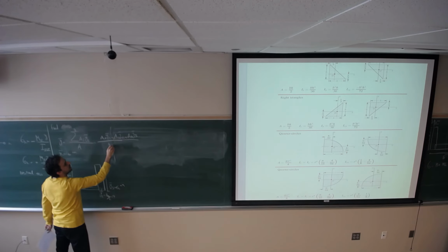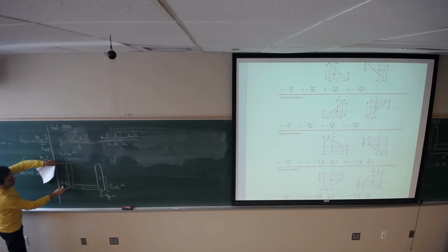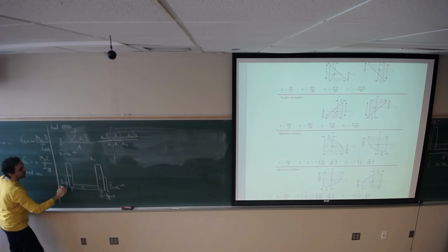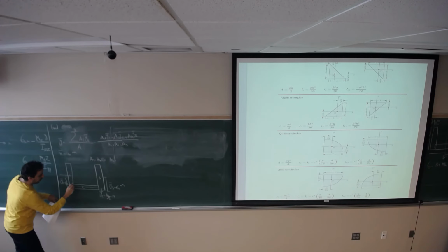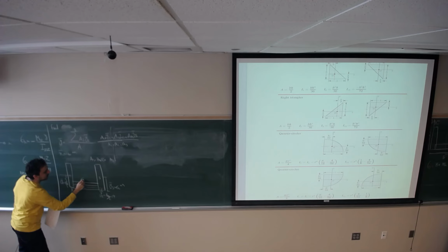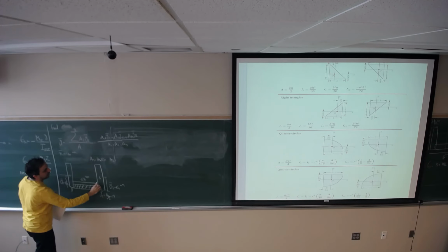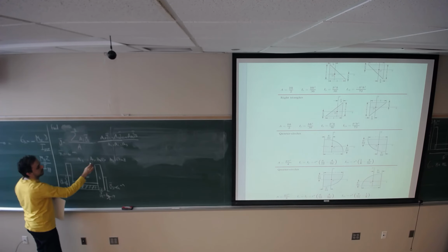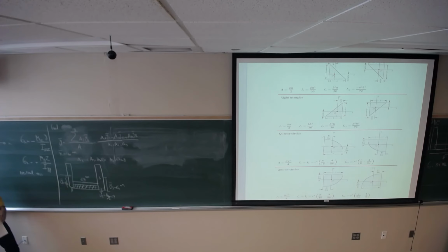Divided by summation of the A. What would be the total cross section? So A1 is 8 millimeter multiplied by 120. A2, from here to here is 64 millimeter, so this cross section is 64 times 8. And A3 is going to be the same as A1. They are identical. Just plug in the numbers.